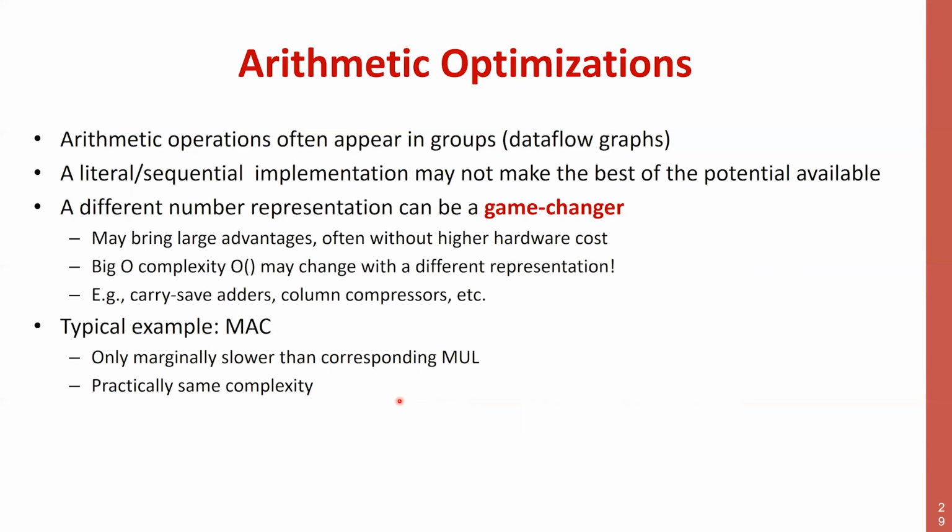So for instance, why are floating point units much faster than libraries that do floating point? For all the reasons that we have seen so far, including the fact that typically I convert from maybe the IEEE representation that I have to obey in the processor into some other representation that is more convenient for doing hardware operations.